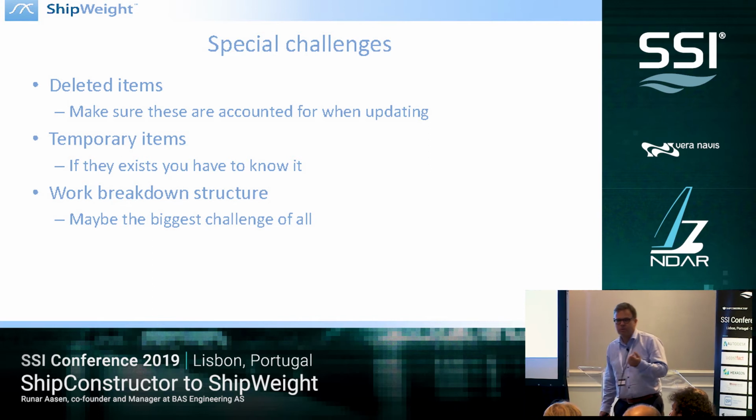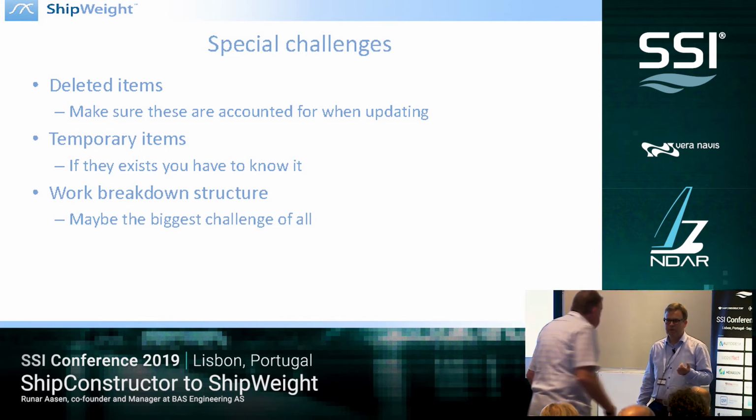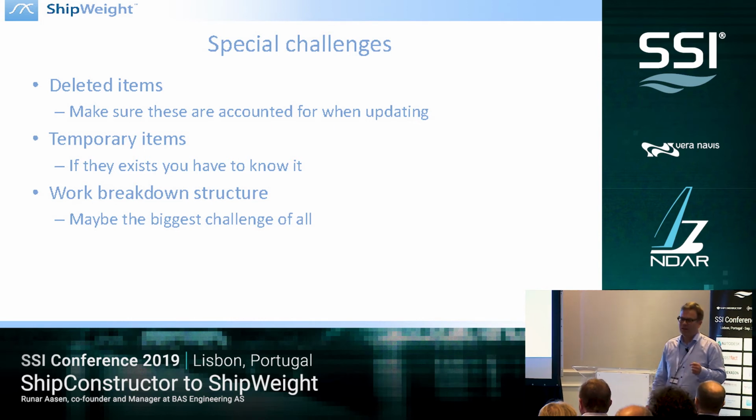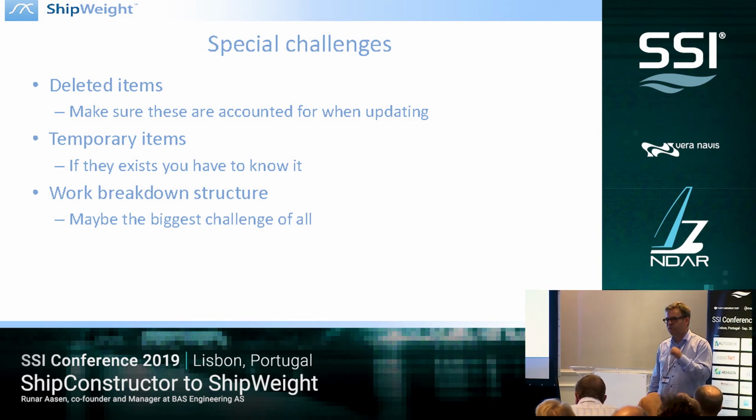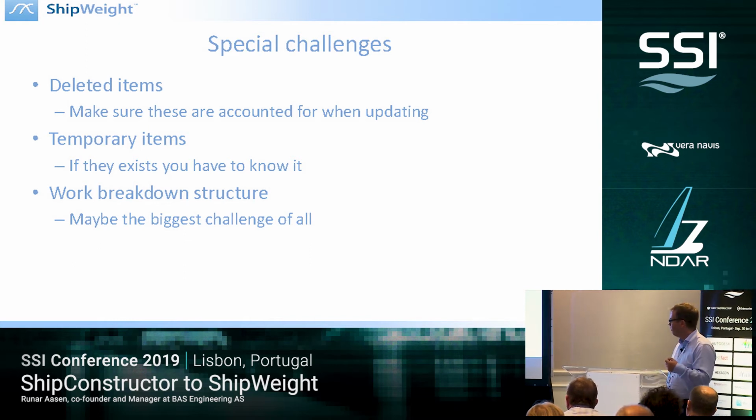And finally, the work breakdown structure, which is, I think, the biggest challenge of all. If you are going to be able to utilize weight data in the future in a good way, and if you're going to do good weight monitoring and tracking, you need to assign your weight data to some sort of work breakdown structure. Okay? And this is often possible in the CAD system. I know it's possible in ShipConstructor, but many times it's not being done.